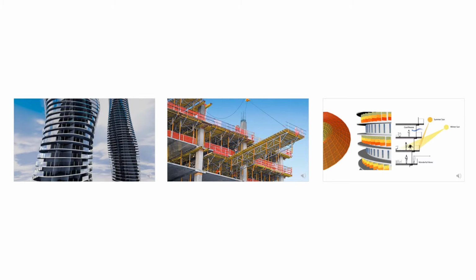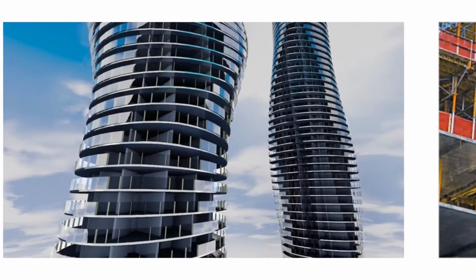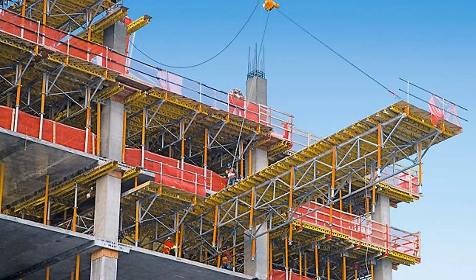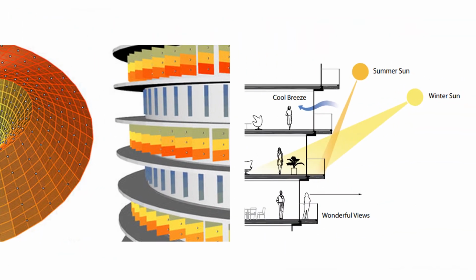Because of the symbolic rotating slab, three structural challenges were given to the structural engineer of this building. First, the traditional concentric loading of columns was not appropriate for the unique design of the building. Secondly, traditional flight tables were not appropriate for this construction because they would have resulted in large unsupported panels when the rotation of the floor plate was more than 2 degrees. Third, the rotating floor plate caused additional vertical thermal transfer issue.